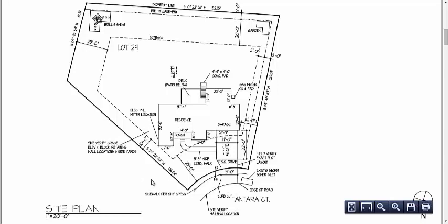And then lastly on this one, a couple things actually. Slope, you can see it defines that the water drains away from the house. That's a good thing. And then the last piece here is you see these funky little numbers here. S, 27 degrees, 22 minutes, 30 seconds. That's what those dashes are, west. And then it gives the last number here of 126.84 feet.